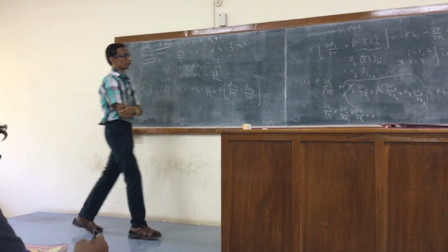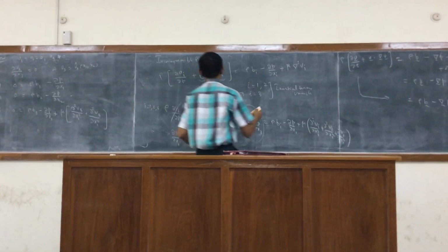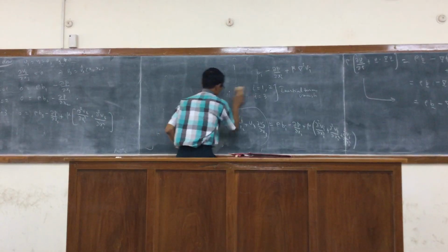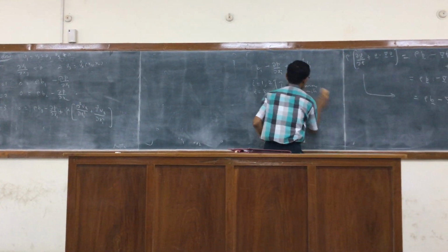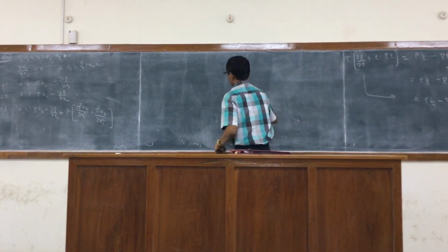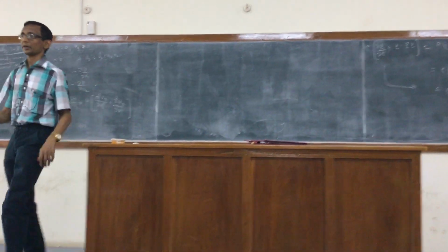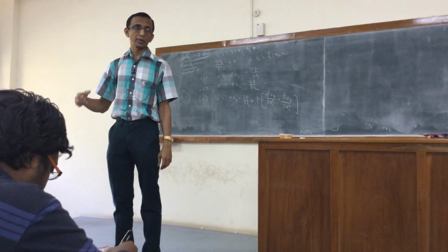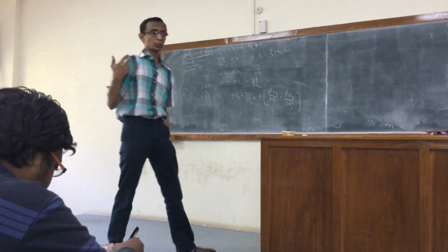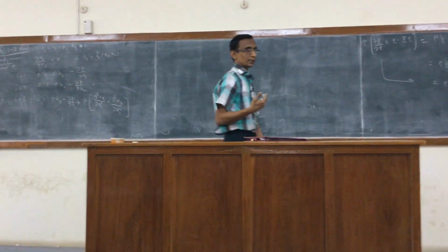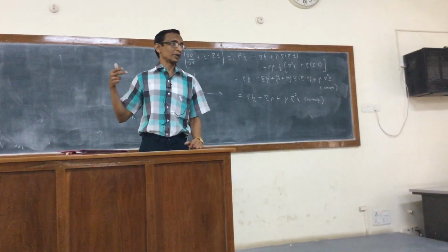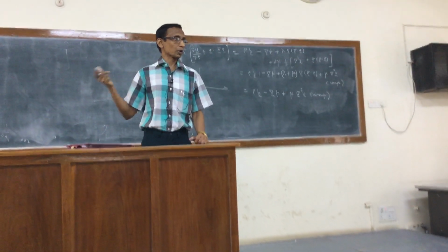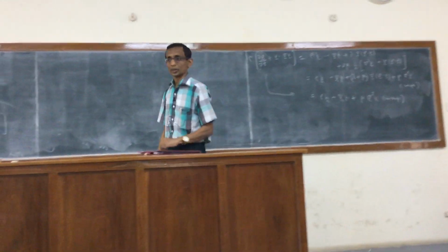We will apply this to a very simple case: flow in rectangular channels. You will soon see that we are limited by the fact that these equations are in the rectilinear coordinate system. Even the simplest case of flow through a tube, which leads to the Hagen-Poiseuille equation, we cannot really handle because we don't know how to write the equations in other coordinate systems. It will be very complicated to solve such problems in the rectilinear Cartesian coordinate system.